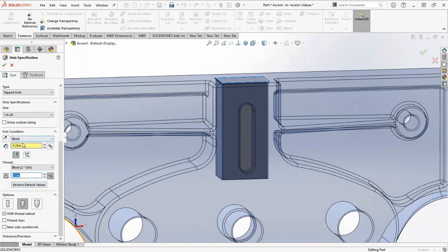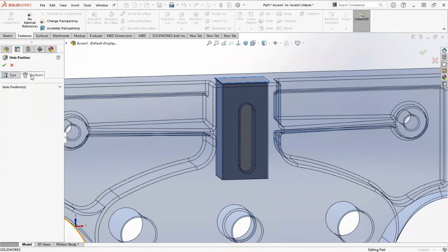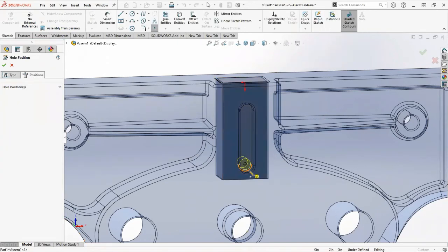See, the nominal distances here are what SOLIDWORKS has for that type of fastener. And when you go in and change it, they turn yellow, just to let you know that, hey, these weren't the original distances built in and associated with that fastener, which is okay in our situation. I'm going to go ahead and go to the position and use referencing to position my hole in the center of this radius there. All right, I'm going to click OK.